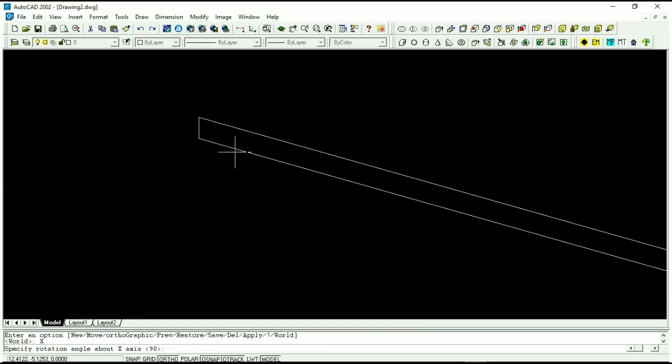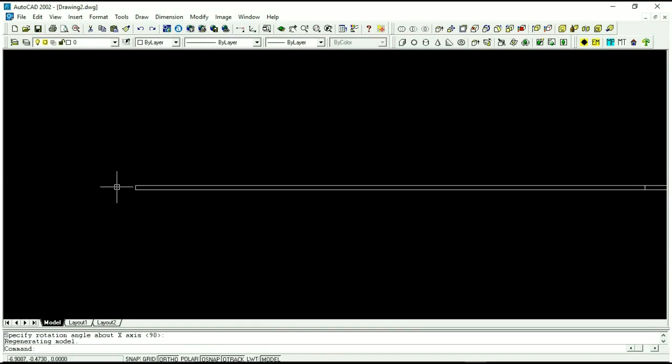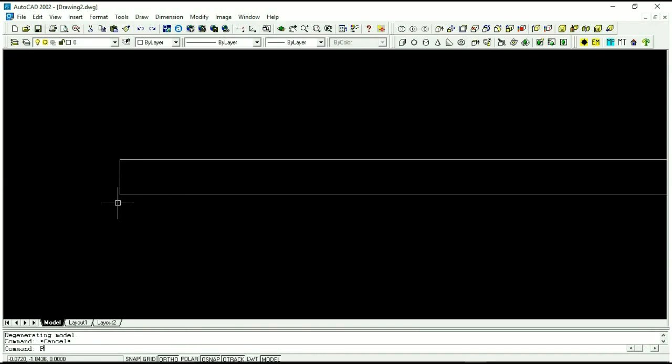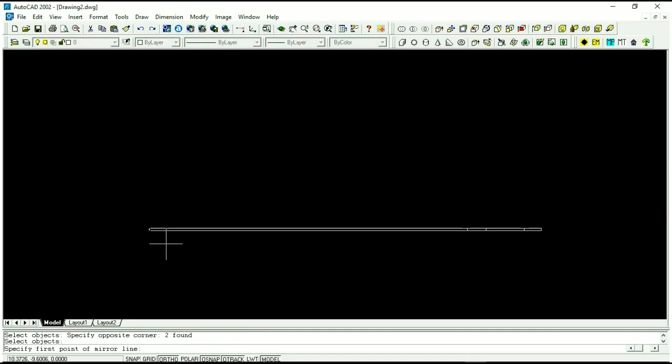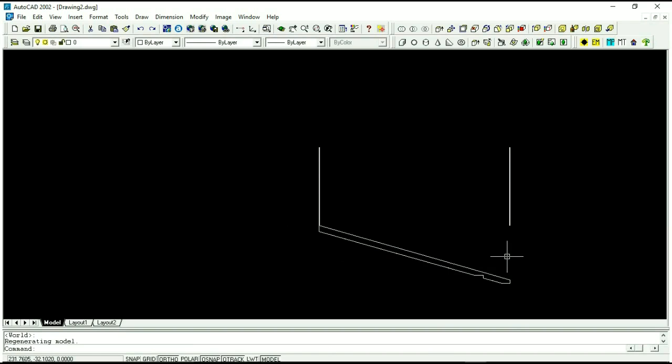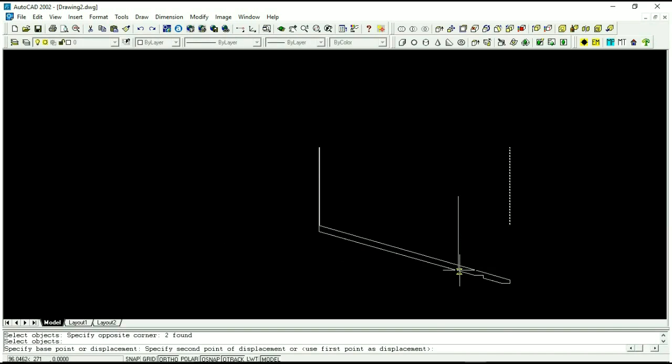That's why I've done that. So if I do a simple UCS X, I'm looking down on the part. I come in here and I do a polyline from the center, half the width, and then I'm going to mirror that. And then I'm going to mirror it about this end, about the length of the rafter. Then I'm going to extrude all of them, some huge number. It needs to be something deeper than the piece. So I just do negative 100. And then I come back, and I need this extrusion to cross the end, so I just drop it straight down.